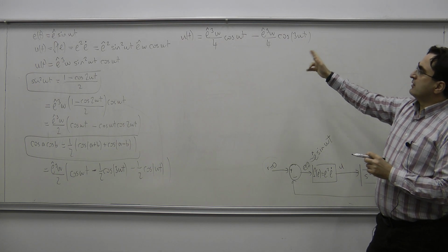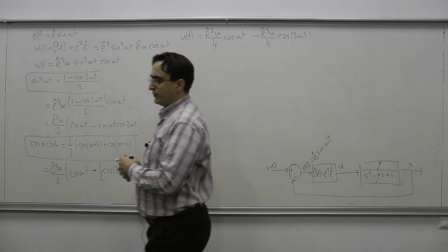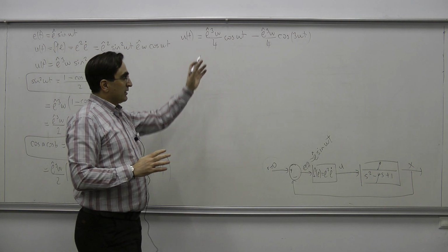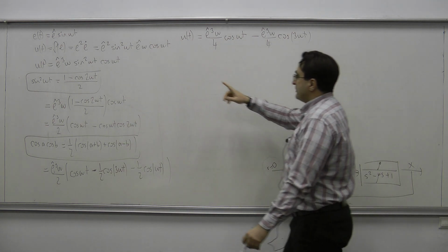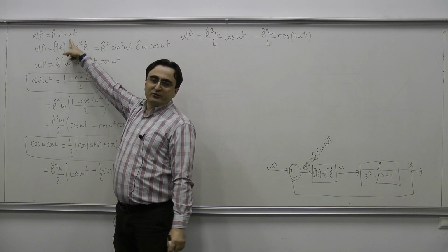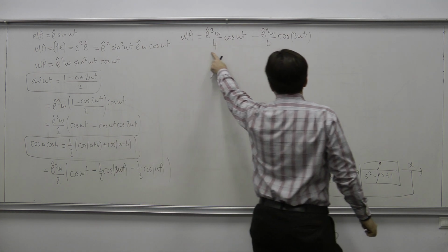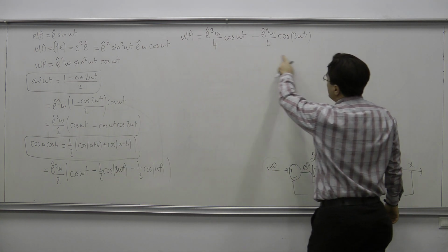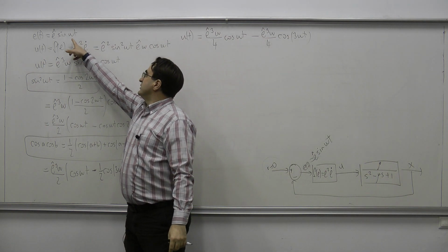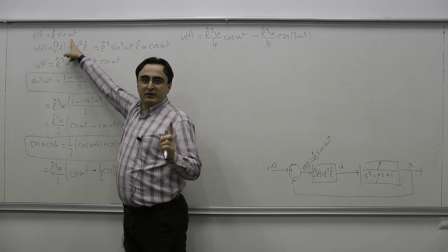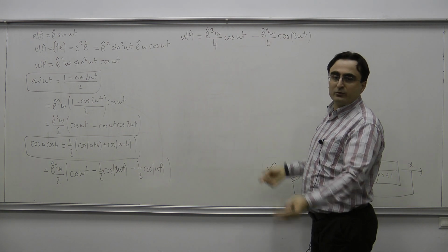So by just looking at this input and output, you need to be able to say, with the knowledge that you have in terms of system theory, that black box is actually a nonlinear system. Why is that? Because I'm supplying that system a pure sinusoid, and if at the steady state I see this output, that means that when I give the system an input at a single frequency, the system gives me output components at other frequencies as well.